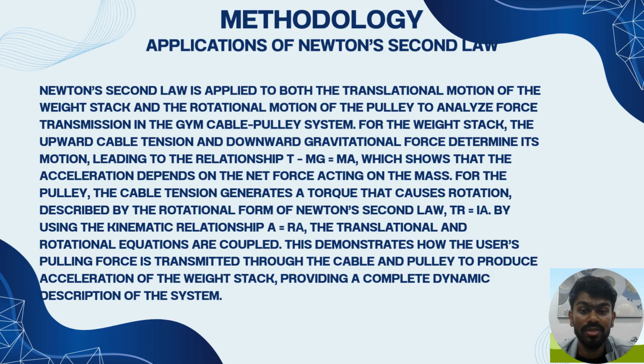For the pulley, the cable tension generates a torque that causes rotation, described by the rotational form of Newton's second law, T R equals I alpha. By using the kinematic relationship a equals R alpha, the translational and rotational equations are coupled. This demonstrates how the user's pulling force is transmitted through the cable and pulley to produce acceleration of the weight stack, providing a complete dynamic description of the system.